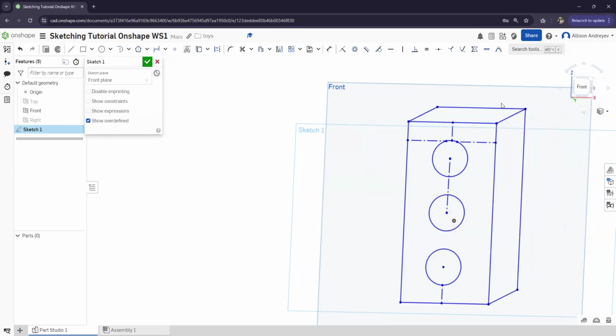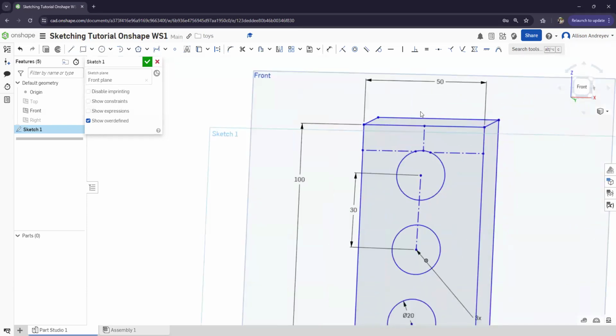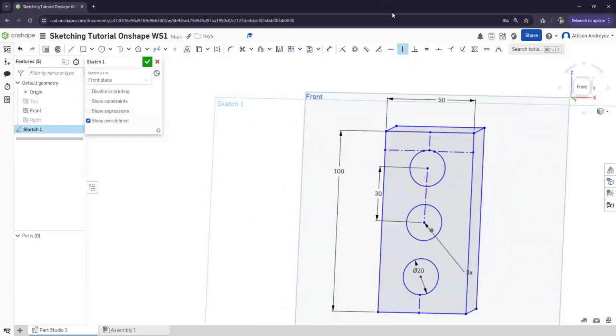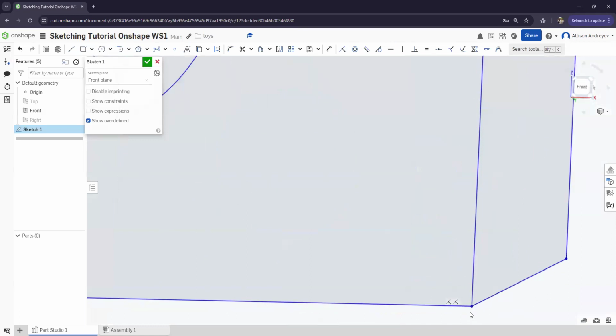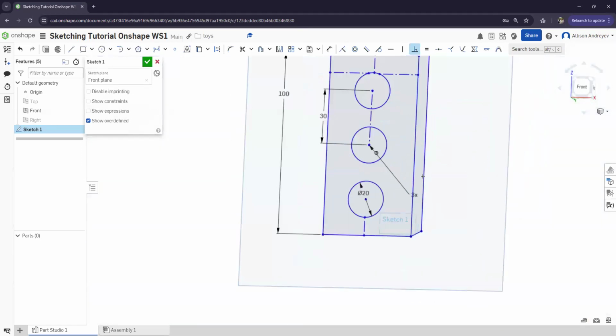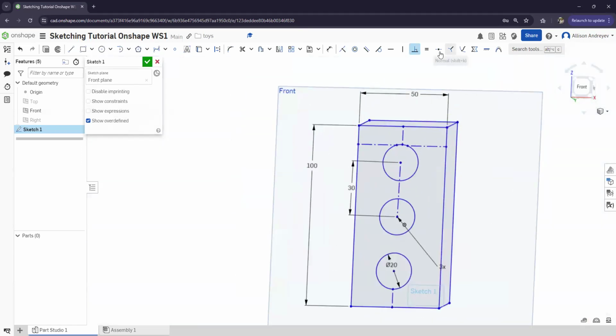So we kind of get to choose the thickness of our drawing here. I'm going to go, this one should be okay. And then to make sure that these are horizontal, I'm going to do that. And to make sure that these lines are vertical, I can click on that and give them that constraint. And is there anything I want perpendicular? There definitely is. So, for example, this line should be perpendicular to here. And though it already is, I'm just showing you guys for good measure how this stuff works.